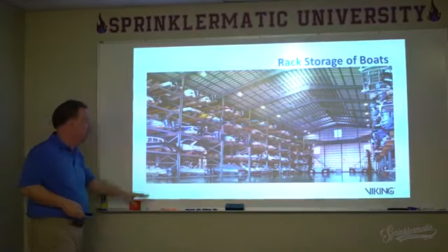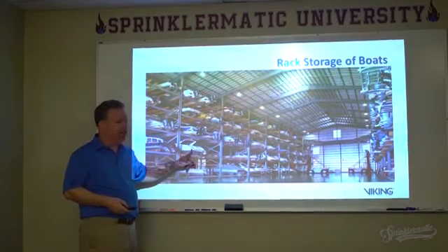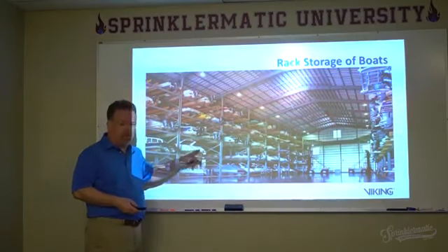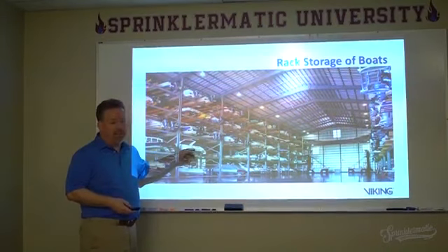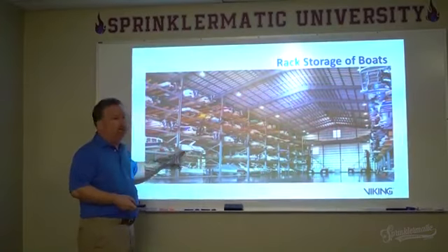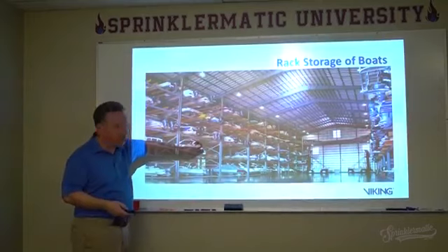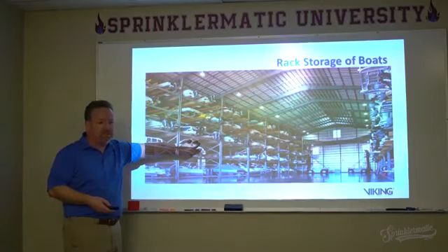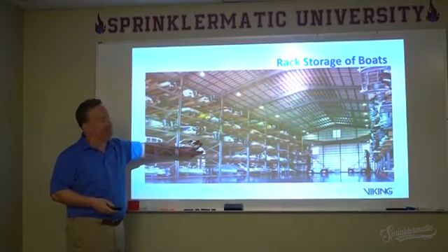And here's the reason why. We can tell you that it's plastic. Okay, great. We know how plastic burns. We know how the foam plastic burns with the seating inside of it. We know that there's fuel in there, so that's going to be a problem. We know that it's in racks. The big challenge with putting sprinklers up here is, if I get a fire in my boat here, what happens? All that water comes out of the ceiling, and where does it go? In the boat.